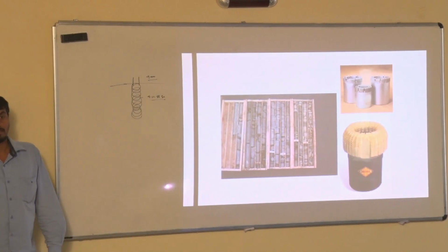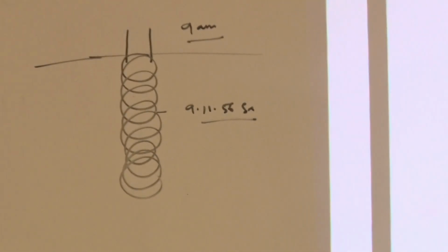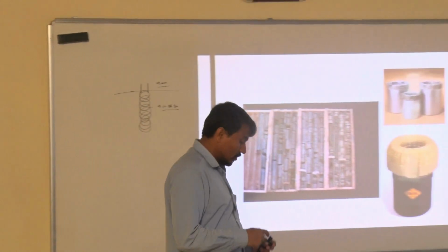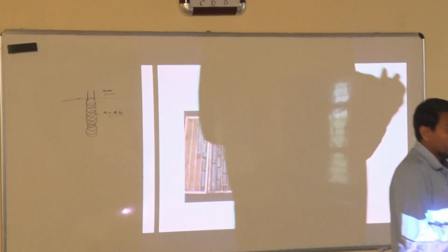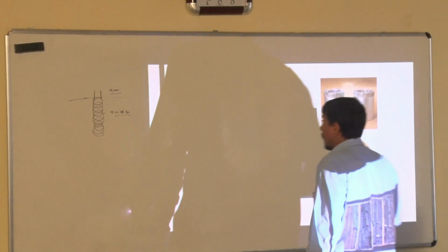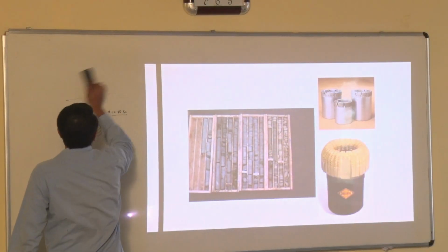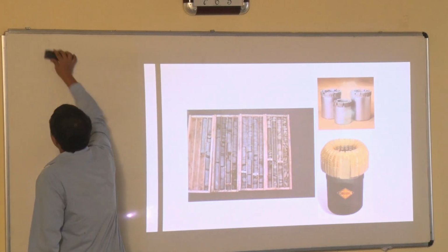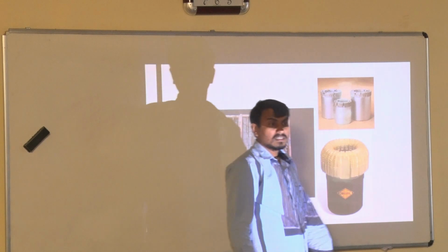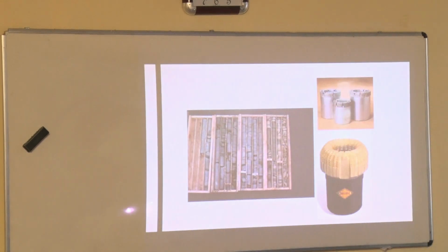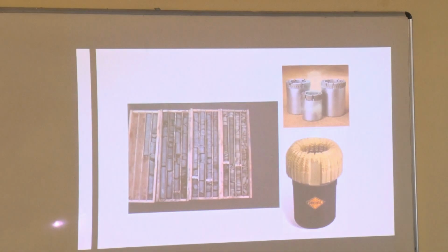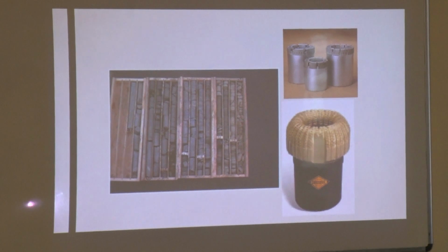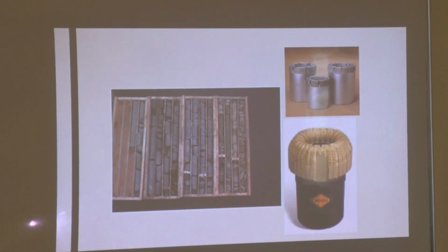They take notes and supply these notes for the geologists to consider when they determine the RQD, because that will also help to accurately pinpoint the location and position of the joint set in the drill core. So finally RQD tells you the population of the joint sets present in the drill core.